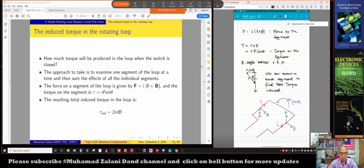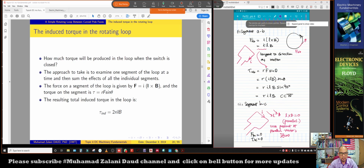So we can calculate the force and torque on each of the segments. For segment AB, for example, using F = I L cross B, we will get ILB, because we know that the direction of L and B is perpendicular. So the force induced is also in the perpendicular direction. Let's say this is FAB.